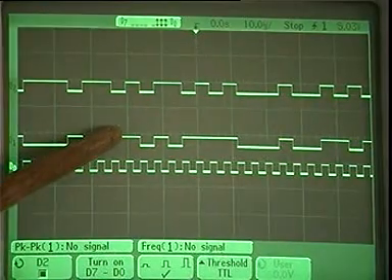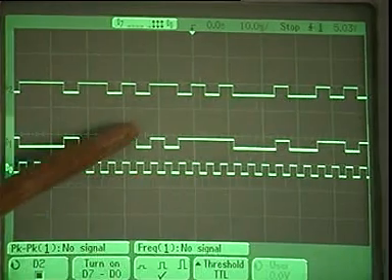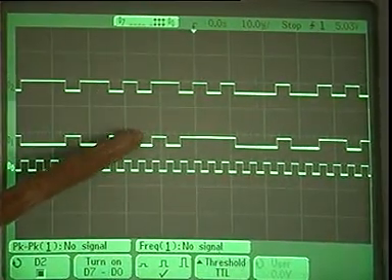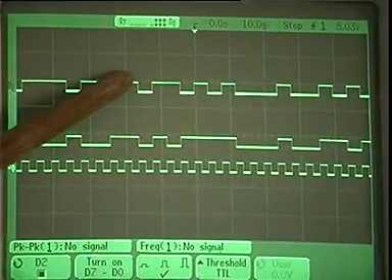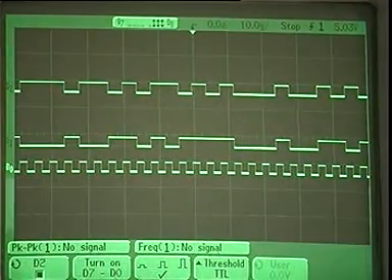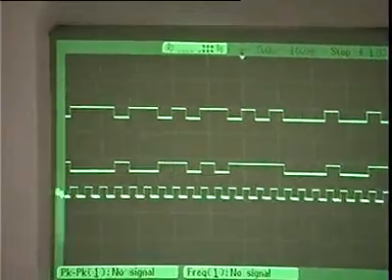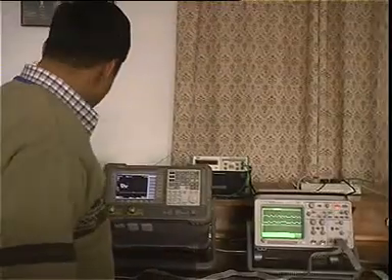At this point, I have a 1, so I come from high state to low state. There is another 1 sitting next to it, so I go from low state to high state. And there is a 0 here, so I stay in that state, and then I keep on going like this. So wherever there is a 1 encountered in the data, there will be a transition from low state to high state or high state to low state. That is NRZM.